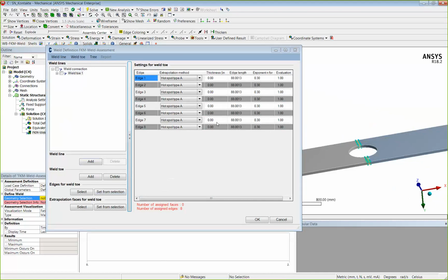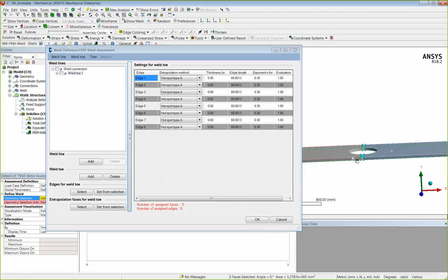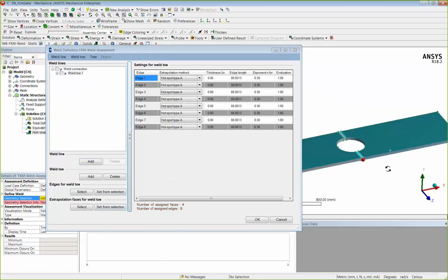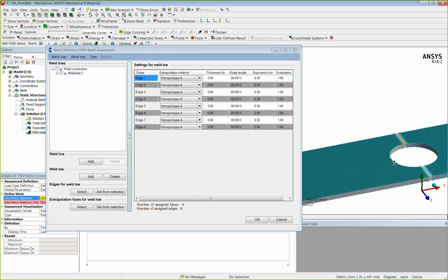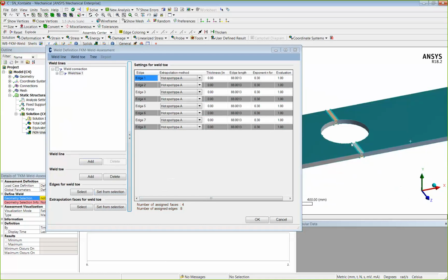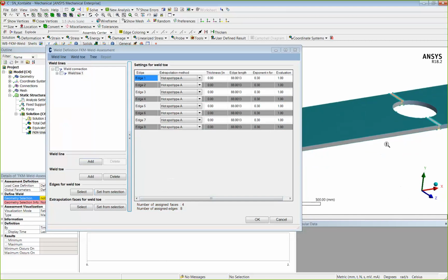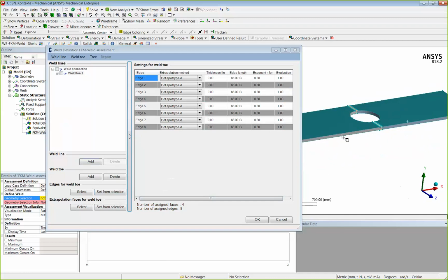These are the surfaces where the paths are to be mapped onto. Now he would know he has to draw paths from here into the surface. What he didn't know right now is how much is the distance. The distance is depending on the thickness of my sheets that are welded. Or if it's thicker than a sheet, I could simply switch to hard stop type B, then it would be a fixed distance.